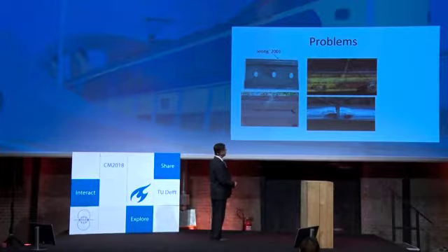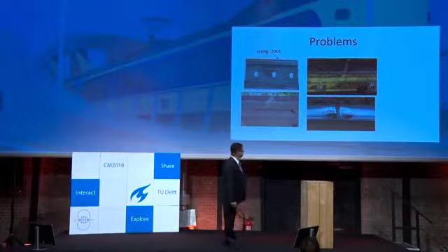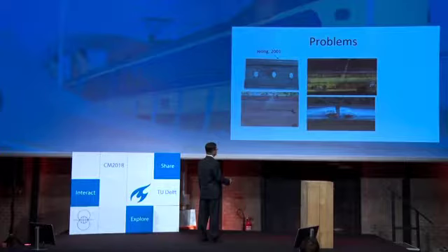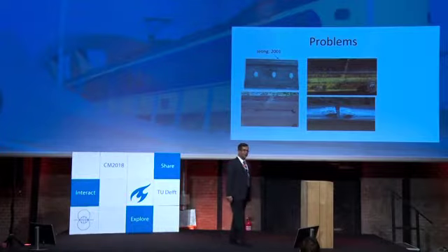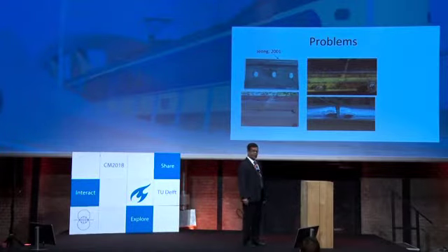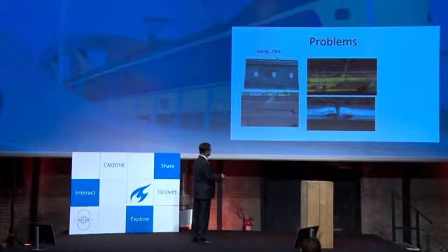Because of severe plastic deformation, you can see material seeping out, which is not good and should be avoided. This is the joint from the track, and this is the failure of the rail. Away from the rail head, some other things are also important. Not so popular in Australia, but elsewhere, in the USA and Canada, it is another common mode of failure. This is the crack of the joint bar. This is the bolt hole crack.